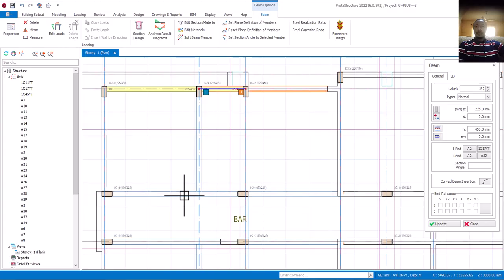Let me look for XL, enter, B, enter. So from here, let me put it at this edge and also this edge. Is that okay? Or let me put it at the center, L, enter. From here to this point, let me click on this, M, enter, that's move, and then let me put it somewhere here. That's the center, isn't it?